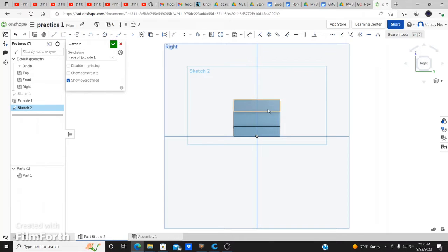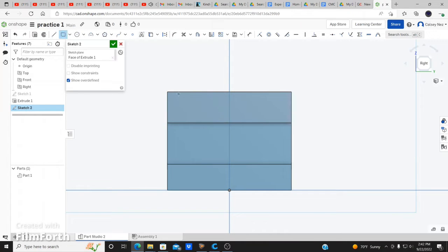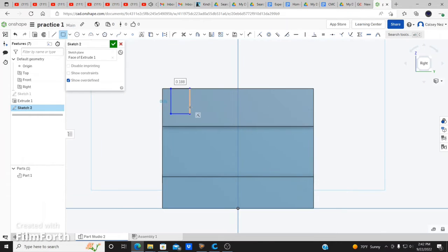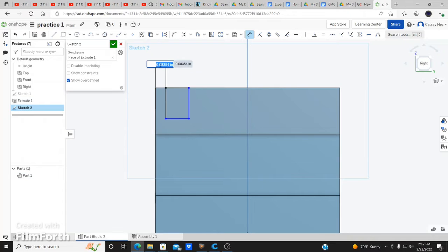So, okay, now we got to here, and I'm just going to add in my rectangle. That's going to be the corner to corner rectangle. I'm going to click right here in this area that's highlighted on the horizontal line, just anywhere right here. We're not going to worry about the dimensions yet until I include that. Okay, now I'm going to add in my dimension from this line to this line, and that's going to be about 0.1. Enter. So that will be my space right here.